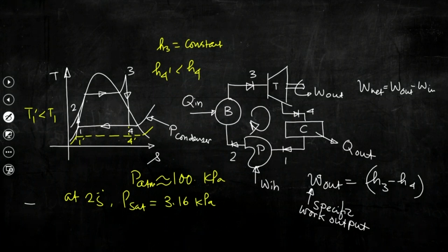So, now since the pressure is way less than the atmospheric pressure, we need to have a special device that will operate at this pressure, and this is what is done in a condenser. So, we can understand the condenser has two important objectives. First of all, it allows the entire unit to operate in a cyclic manner.